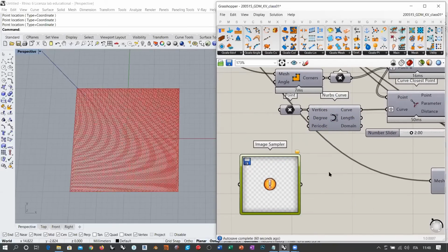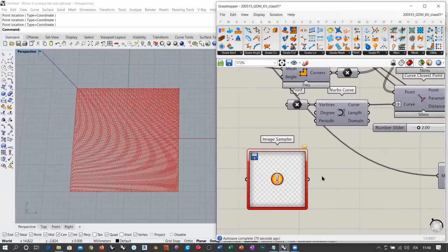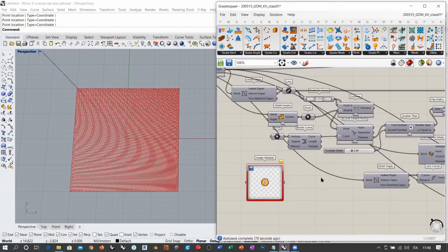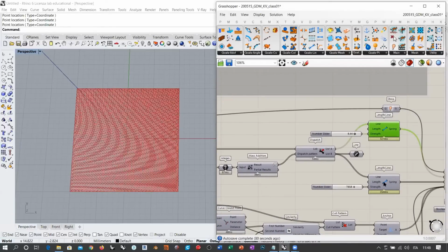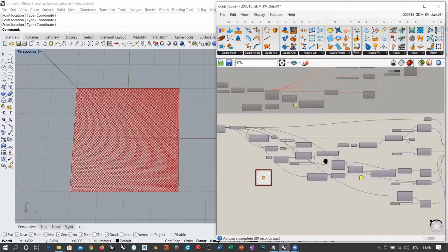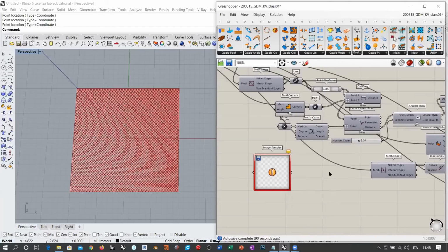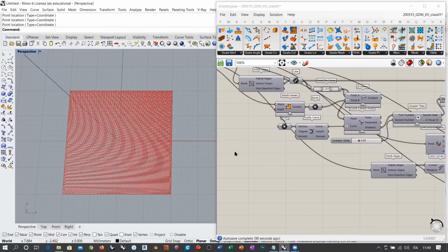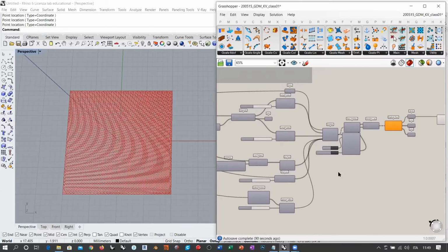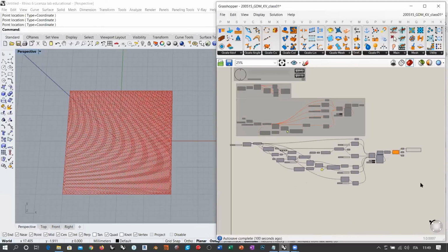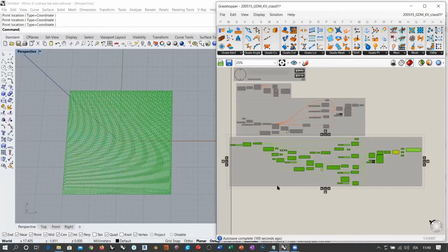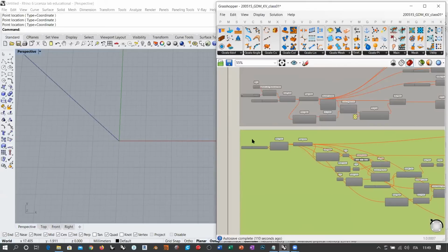So I leave it as a new development that you can easily do by yourself. It is just painting an image in grayscale and associating white to, I don't know, more elastic edges and black to less elastic edges. In that case, you can simply use any photo editing program to create the corresponding distribution of elasticity or rigidity along your mesh. So this is something that I would say is an indirect approach to differentiated behavior for inflatable structures. Now let's go and analyze a direct approach, okay, which is...